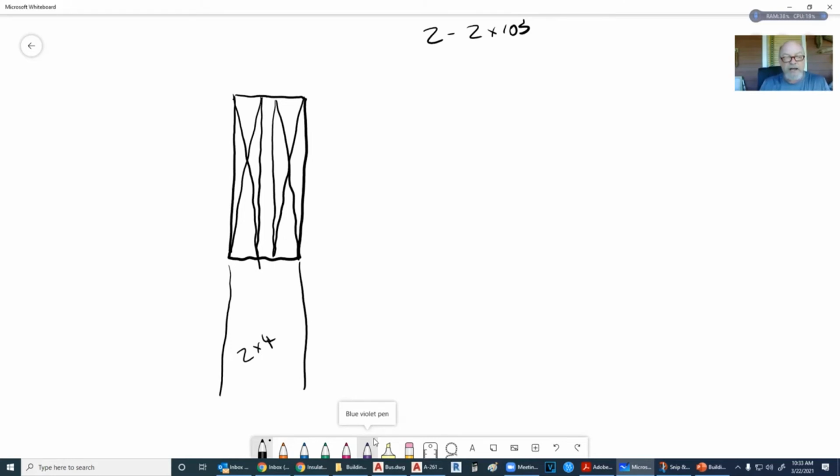My instructor said to build a proper header, because these are 1.5 inches, if I put 2 of these together, that would be 3. Well, this wall is 3.5 inches. So what do you do with that other 1/2 inch? You take a piece of plywood and stick it in there to take up that space. That's what I was taught. Then you nail or screw all of this together and it becomes one great big heavy duty unit.